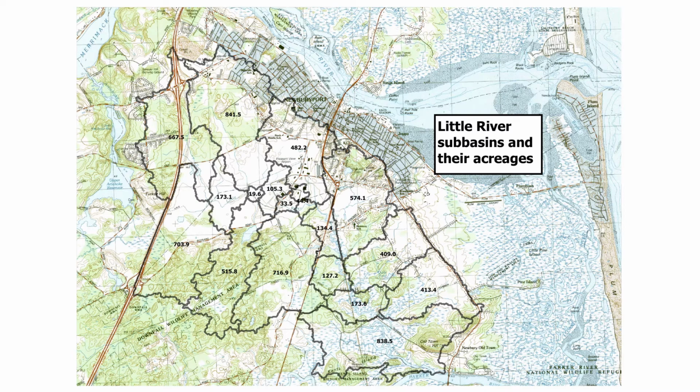It has great vertical accuracy, that's of 15 centimeters, which is about 6 inches, and a horizontal resolution of 1 meter. This level of accuracy and detail is very suitable for flood modeling work.